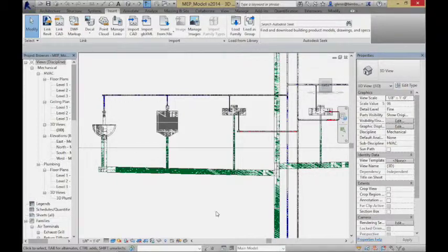When things are running straight up and down, I'll call that a riser. I tend to call that a lateral. Okay, so that all works together. As you go through and do this, the size of the pipe necessary to carry everything away is determined by how much load you're putting onto it. If I have many, many loads contributing to the pipe, this pipe's going to have to keep getting thicker and thicker.